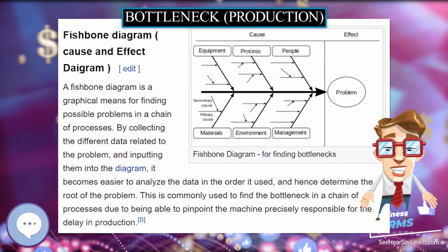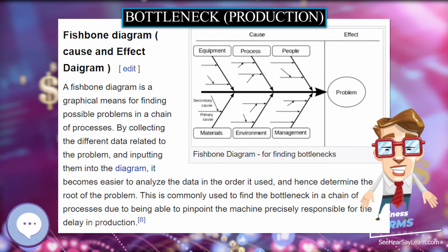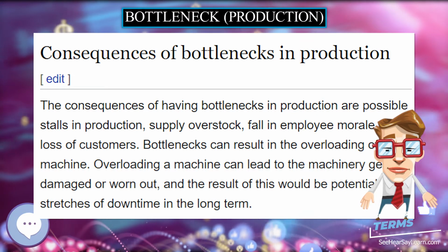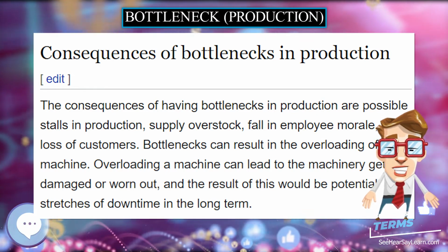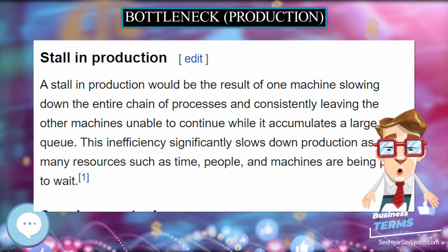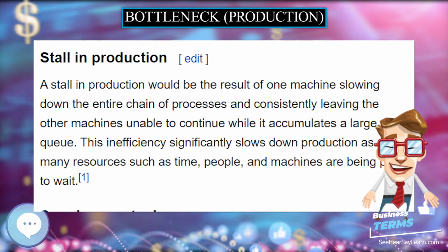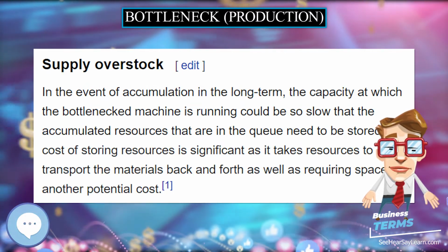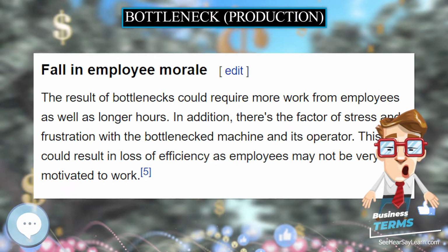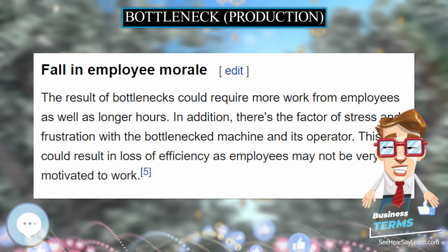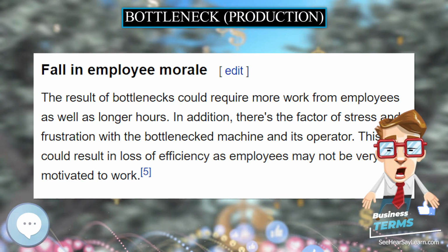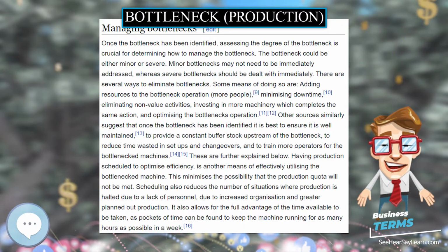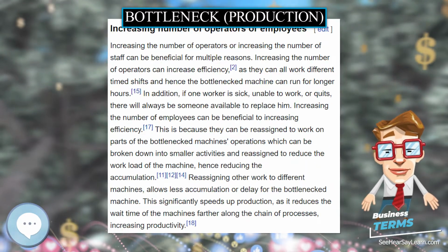Another example is in a surface mount technology board assembly line with several pieces of equipment aligned. Usually the common sense strategy is to set up and shift the bottleneck element towards the end of the process, inducing the better and faster machines to always keep the printed circuit board, PCB, supply flowing up, never allowing the slower ones to fully stop, a strategy that could result in a deleterious, or damaging, and significant, overall drawback in the process.